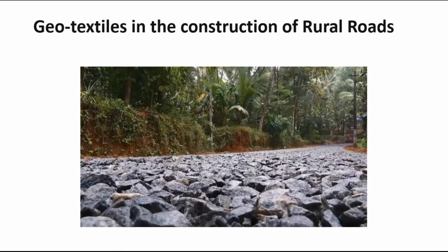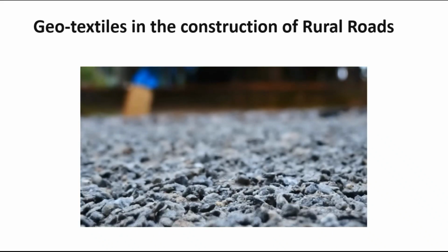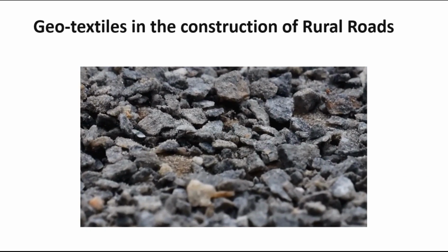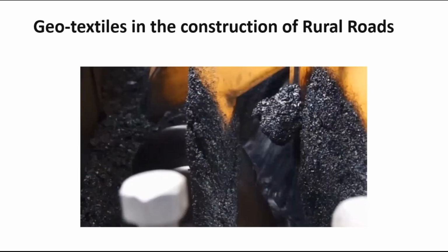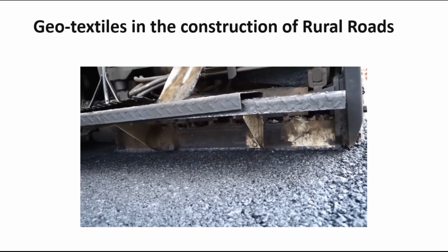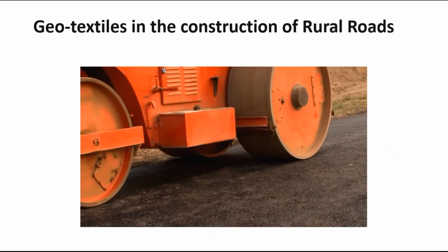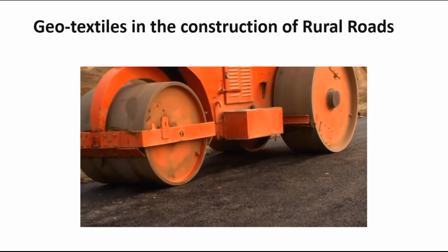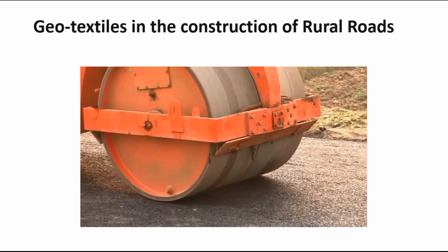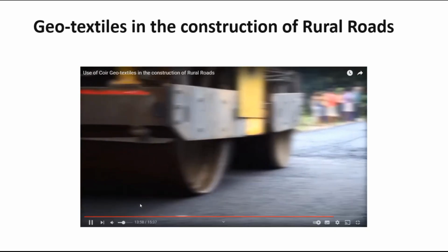The grade 3 layer is then spread in the same manner as grade 2, and the screening material is again applied to fill in the pores. But at this stage, instead of binder earth, slow setting bitumen emulsion is applied as prime coat for bonding. Above this base layer, rapid setting bitumen emulsion is applied as tack coat, followed by 20 mm thick premix chipping carpet using natural rubber modified bitumen or NRMB or BG30 grade bitumen. Finally, a seal coat using the same bitumen is spread over to finalize the surface layer.